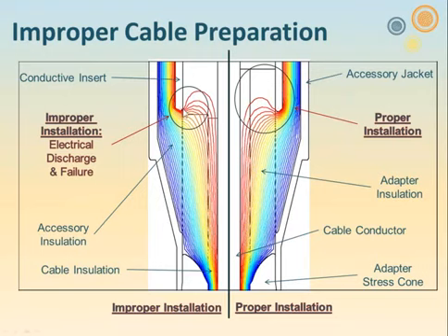It's going to start buzzing, partial discharge. That partial discharge is going to start eroding the insulation in this area. It's going to erode it continuously until eventually we have a puncture out the side here.